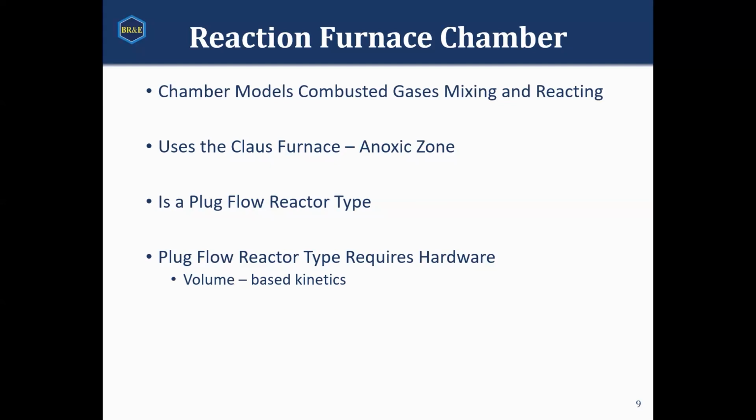Now with the plug flow reactor type, this is a volume-based kinetic reaction set that we are using. With it being volume-based, we suddenly become very interested in the volume of the vessel. The volume of the vessel helps us determine residence time of our reaction to determine how far along our reaction will go. In order to figure out the residence time, we will need that volume. In order to figure out the volume of our reactor, we are going to need to put in some hardware information.